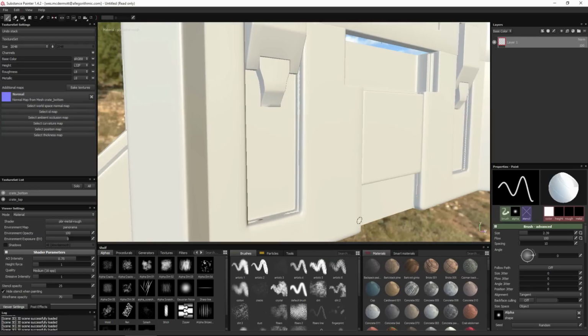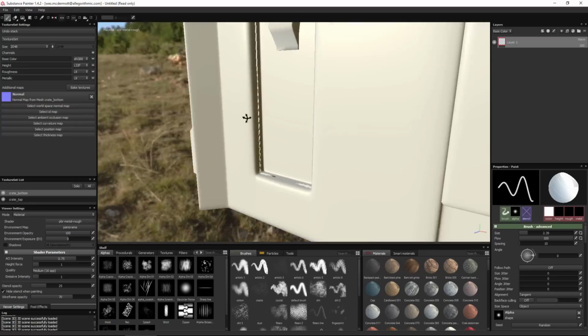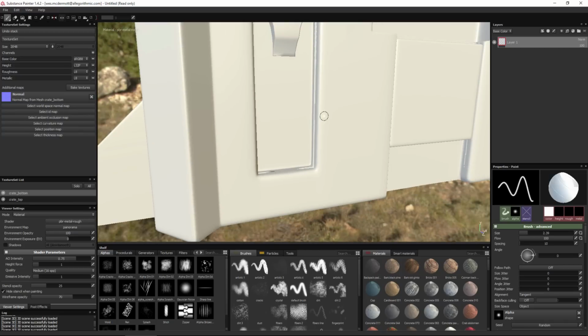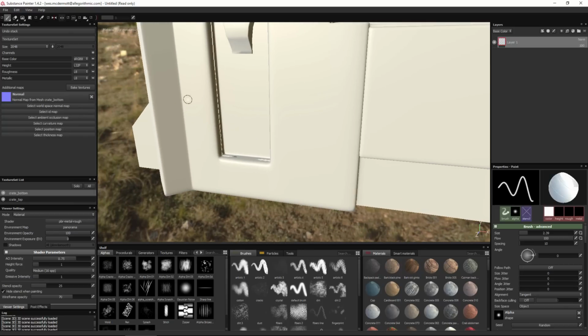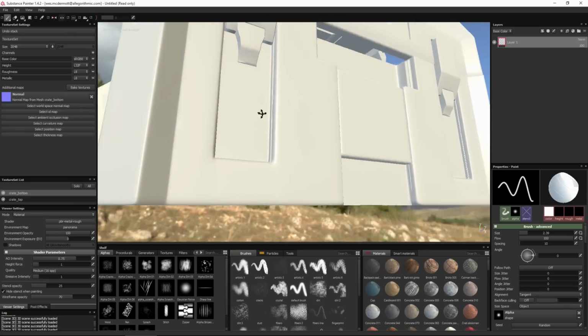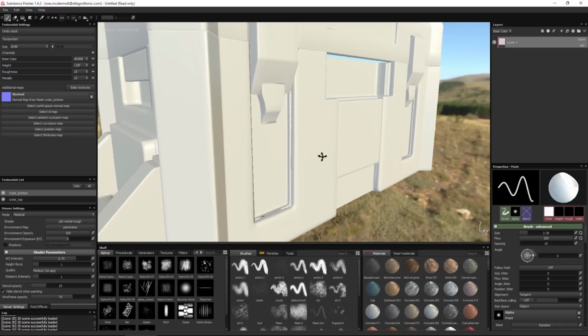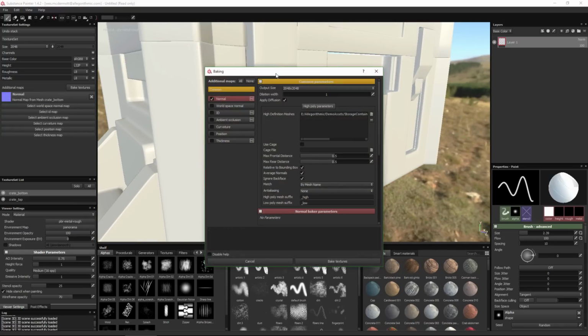And so now you can see some of the errors I'm getting here in this mesh itself. So this ray now is too far, and even though it's not intersecting with the other meshes, it's still projecting back on itself because the ray is too long. It's shooting all the way across and hitting this other edge here. So we're getting this kind of issue. So with this, you can see that it just becomes this balancing act of knowing how far apart your meshes are. The further apart your meshes are, the farther the ray needs to be, but you don't want too high of a value, and you definitely don't want too low of a value.